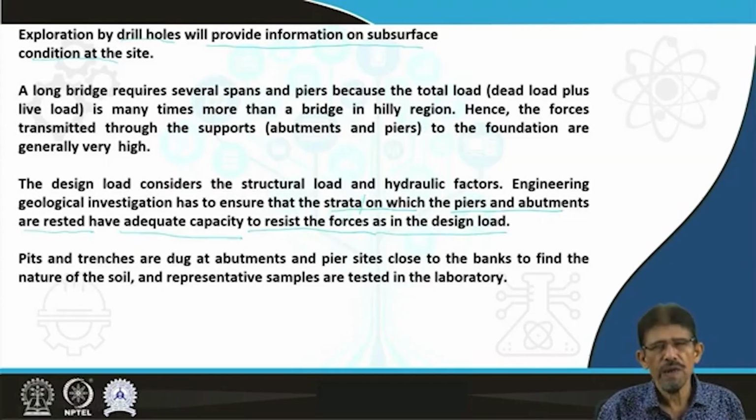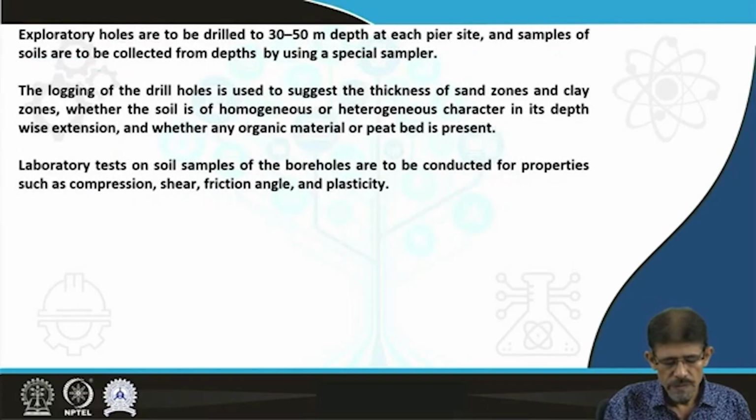For this, we adopt three methods. One is the development of pits, another is exploratory drilling, and another is creation of trenches to see the actual condition lying below the abutments or below the piers, etc.